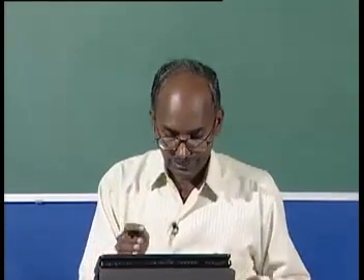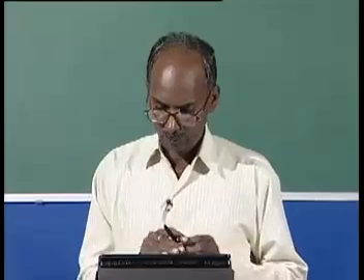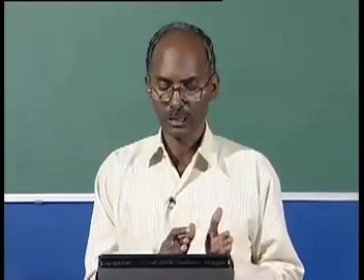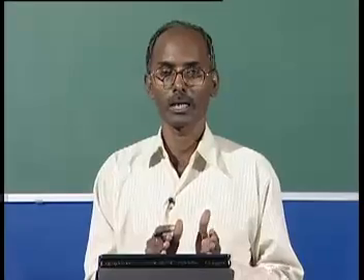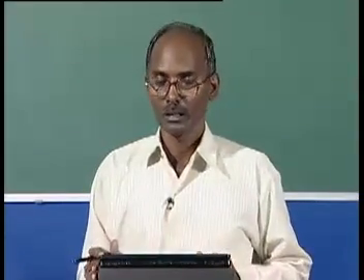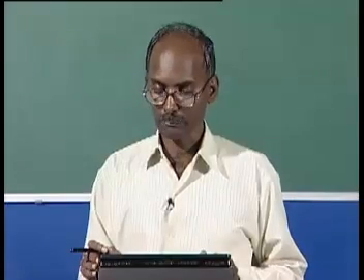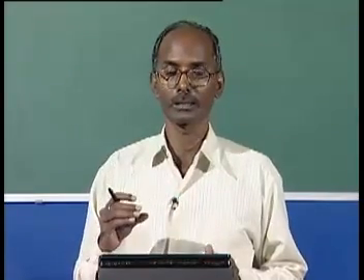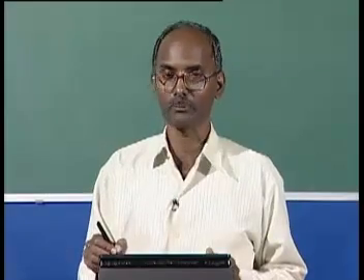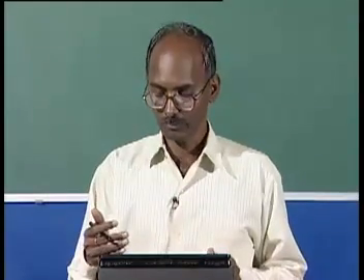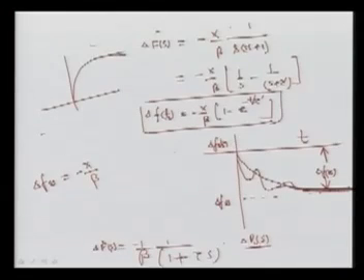So in this lecture, to recap, we modeled this load model, then we analyzed the steady state response and the dynamic response for the primary automatic load frequency control, and we found that some error exists. The error is not only in the negative direction, frequency fall, but also in the positive frequency change: when the load is released, the change in the time domain will be like this, a rise in the frequency when the load is reduced, and this magnitude will be the change in FSS.